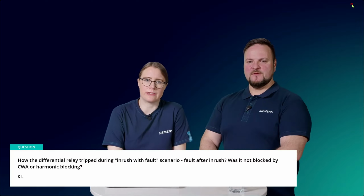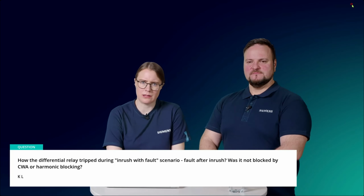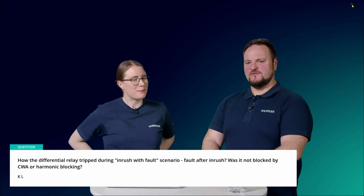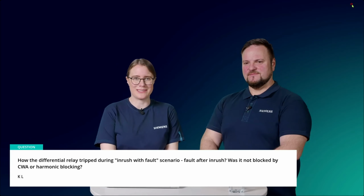Okay, next question. How did the differential relay trip during an inrush with fault scenario, a fault after inrush, which is not blocked by CWA or harmonic blocking? I would say you already explained a little bit that this is a specialty of the CWA internal fault detection, exactly to detect such kinds of faults.